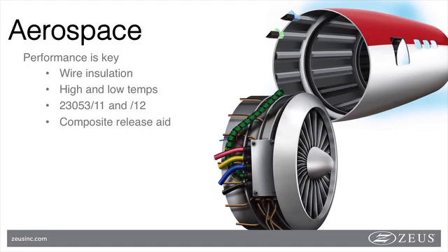Dual shrink, the combination of an outer layer of PTFE heat shrink and an inner layer of FEP heat shrink, can make an excellent splicing aid. The inner layer of FEP will melt and flow into spliced connections when exposed to the temperature required to shrink PTFE, which will result in a moisture-proof splice that is encapsulated with a dual layer of protection.